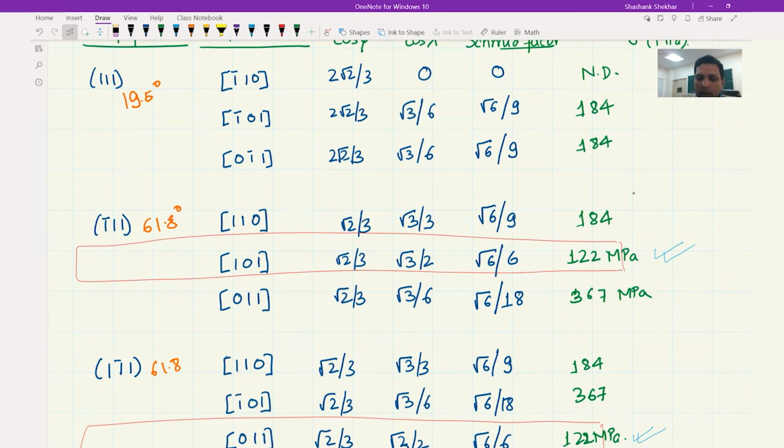So that gives you an understanding of how to find the dislocations that would start to move. So within a given slip system, which particular dislocation system starts to move, and what would be the stress required given the critical resolved shear stress. And we also realize that critical resolved shear stress is something equivalent to a yield strength in polycrystalline materials. So these are some important concepts that we got to learn today, and we also solved some problems with that. So with that, we will come to the end of this lecture. Thank you.